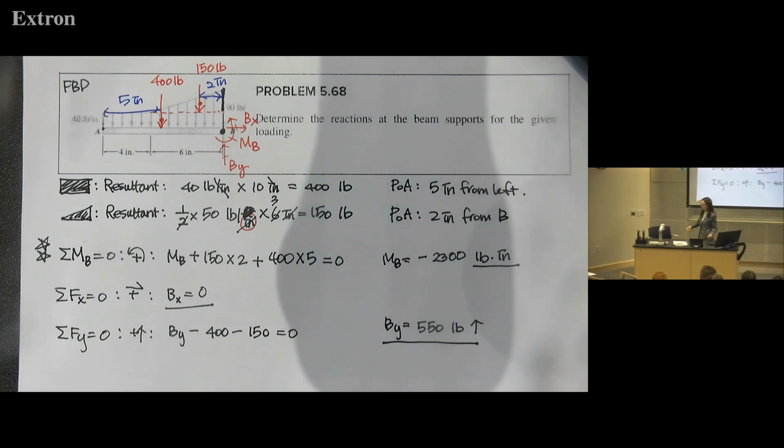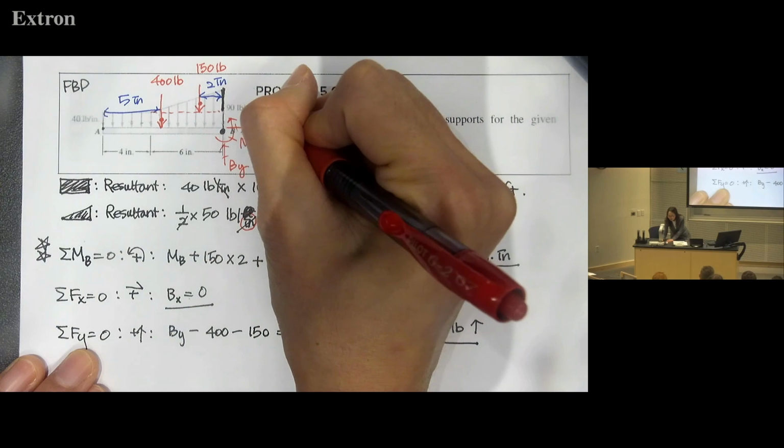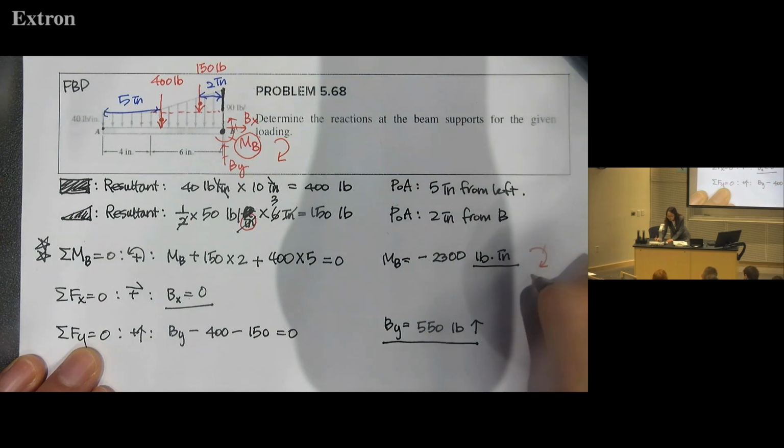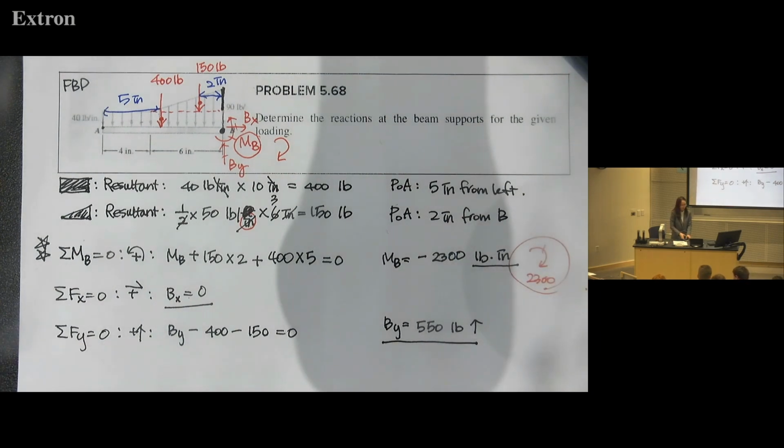Okay, so I show you this one here. So MB is actually this direction, so this direction, and then this. Okay. So for that, I know what you mean. So here is the cantilever beam. This is fixed, and then this is open, okay? And then there is a load here, okay? Then this beam will deflect something like this, right? What is the moment direction induced by the force? This direction, right? And then it is counterclockwise direction.